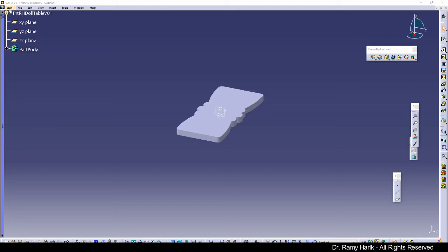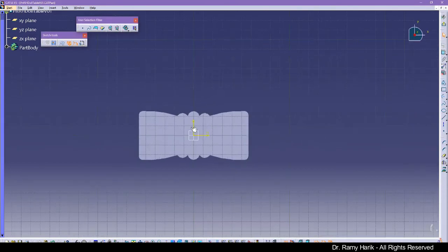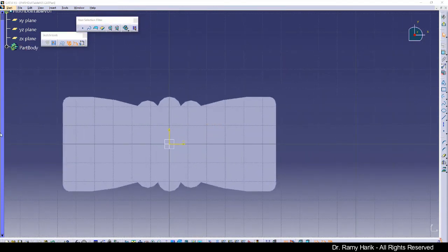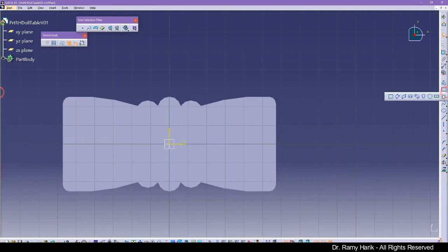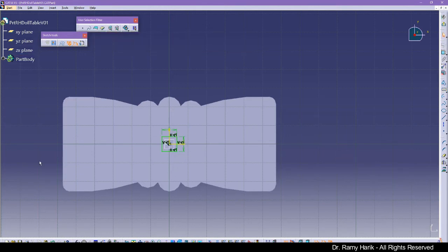So let's go ahead and create the pockets at the top. So I'm going to open the sketch, and in here I'm going to demonstrate a cool feature. What I'm going to do is something called multi-pocket. So first of all, let's go ahead and click a centered rectangle at the center. So it's our 8 by 8 square. So I'm going to put 8, 8, and this is what we have.